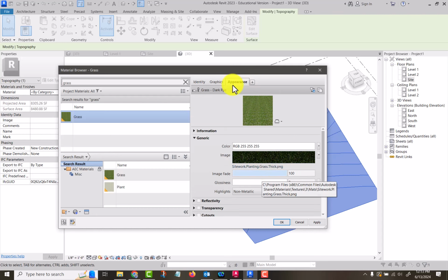Now we just placed points at random in there, but this method is good in that you can bring in a two-dimensional drawing, whether it's an AutoCAD drawing, or a PDF, or even a photograph, or a JPEG image or something that has contour lines, and then you can just pick points and trace across them, which is what you're going to do in one of the assignments, okay?